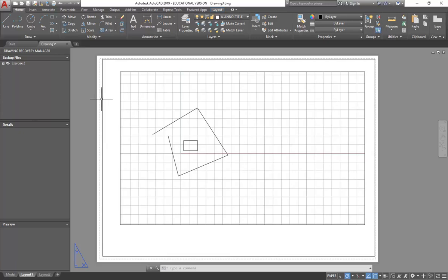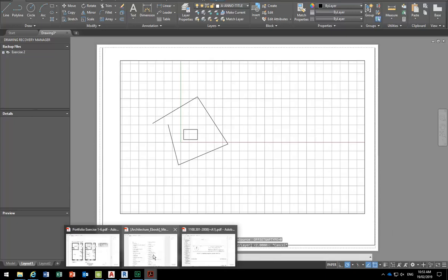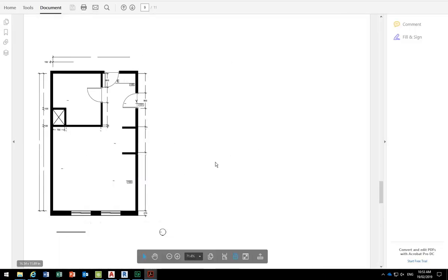And then I can explode this rectangle. Selecting it, click explode, and then make sure that the lines I want, I don't really want these lines at the top, and I'll keep the sides for now though, and then I'll maybe offset and start setting up the title block. So again, you don't even need to have it going the full length of the page like you'll see it does in a lot of these technical drawings. You can do one that's a bit more stylised.